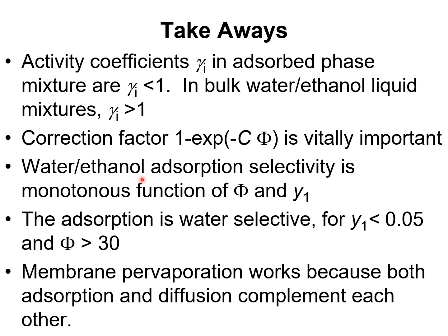The water ethanol adsorption selectivity is a monotonous function of both phi and the mole fraction of water in the bulk fluid phase mixture. The adsorption selectivity is in favor of water if the composition in the bulk liquid phase is smaller than 0.05 for water.